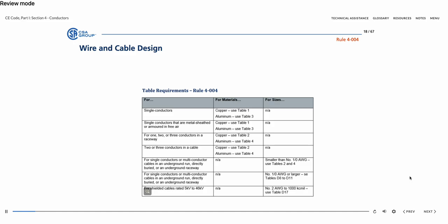Before you can apply Section 4 requirements, you need to know and understand the foundational and physical design for conductors. Conductors can be bare, covered, or insulated. The purpose of insulation is to separate the conducting surfaces by a dielectric material, poor conductor of electrical current, or airspace. The insulation has a degree of resistance to the passage of current and to disruptive discharge that is sufficiently high for the condition of use in order.